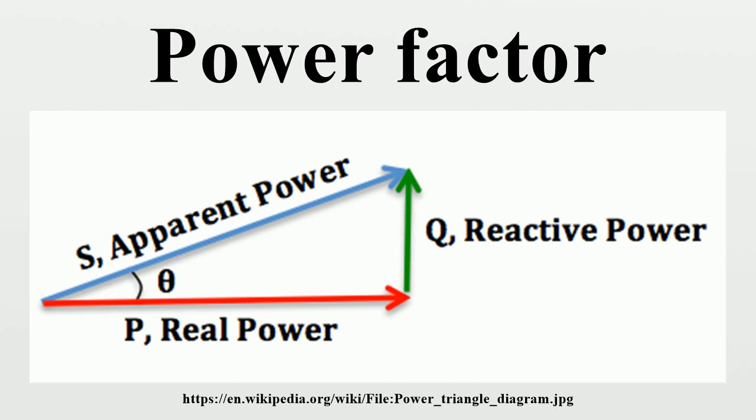Power factor correction brings the power factor of an AC power circuit closer to 1 by supplying reactive power of opposite sign, adding capacitors or inductors that act to cancel the inductive or capacitive effects of the load, respectively. For example, the inductive effect of motor loads may be offset by locally connected capacitors. If a load had a capacitive value, inductors are connected to correct the power factor. In the electricity industry, inductors are said to consume reactive power and capacitors are said to supply it, even though the energy is just moving back and forth on each AC cycle.